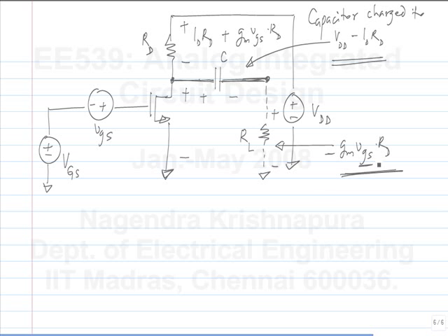So similarly, I can do the same thing to add the input increment to the input bias. If I assume that the input increment is above a certain frequency, I know that the bias is at DC. So I can use a stage which passes the increment at high frequencies, that is beyond a certain range of frequencies, and includes the bias below a certain range of frequencies. And how do I do that? I use a similar network.